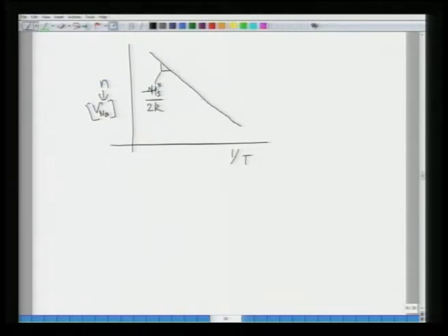If the sodium chloride was impure and you start coming from low to high temperature, up to a certain temperature the concentration of sodium vacancies due to extrinsic impurities is constant, because the extrinsic impurity concentration does not change as a function of temperature.